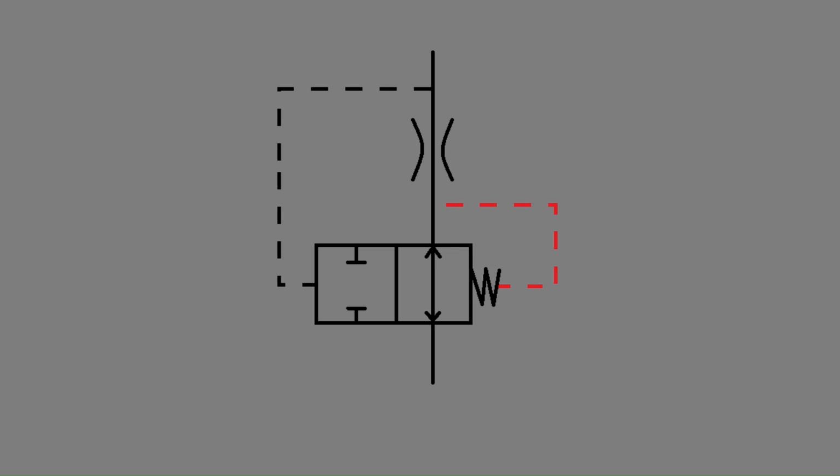It will modulate open and close, trying to keep the forces applied by the high pressure signal equal to the low pressure signal plus this spring. When the pressure drop is lower than our targeted value, that means our flow is also too low. When the pressure drop is low, the differences between the high and low pressures will be low. With the added force of the spring, the valve will modulate open to allow more flow.